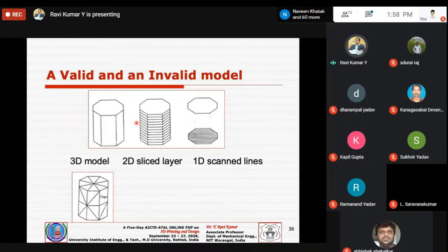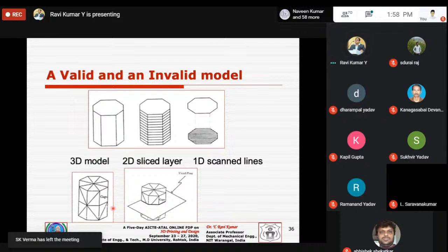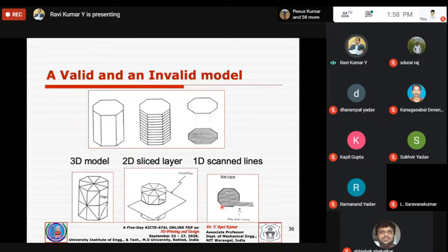But if there is an error we have been talking about, where a triangle got missed and formed a gap, then at that gap, while slicing with your slicing plane and trying to get a closed contour, you never get a closed contour because this triangle got missed. It would have been a triangle here and a closed contour, but because of that gap, your nozzle gets confused.